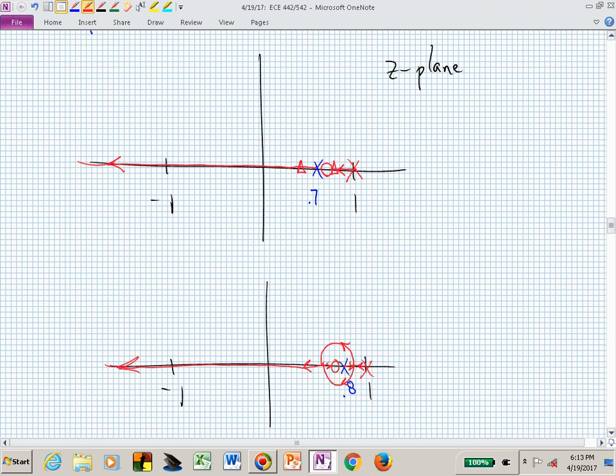And what's the possibility now? You've picked a gain k based on your model at 0.75. Now, you're probably going to have the gain put you with a pole there and another pole right there in the closed loop. Meaning one of those 2 closed loop poles is almost being canceled by the 0. You've now zipped around the 0, and the other one is at the 1/2 location or close from your original design.